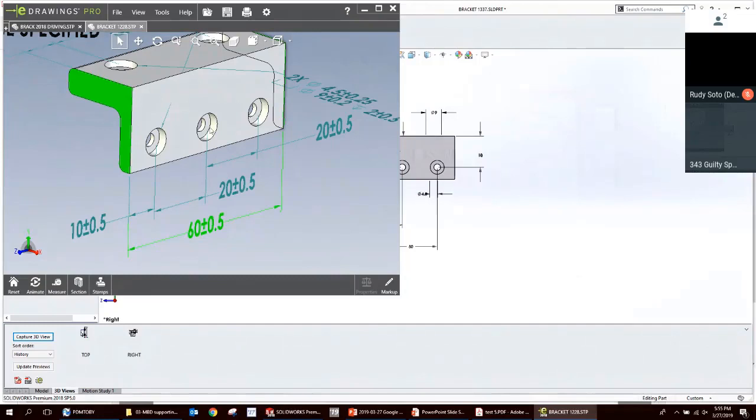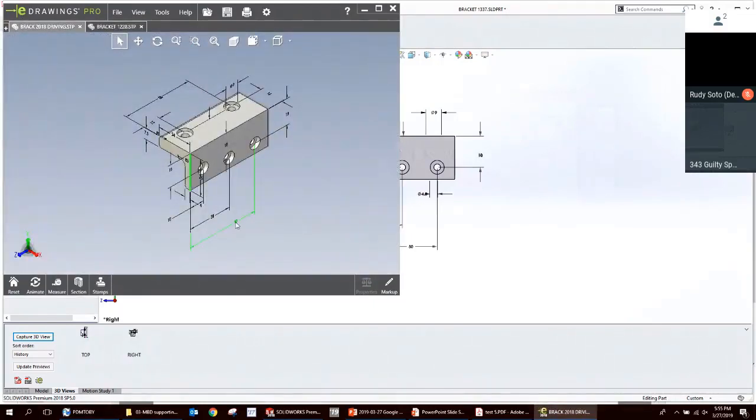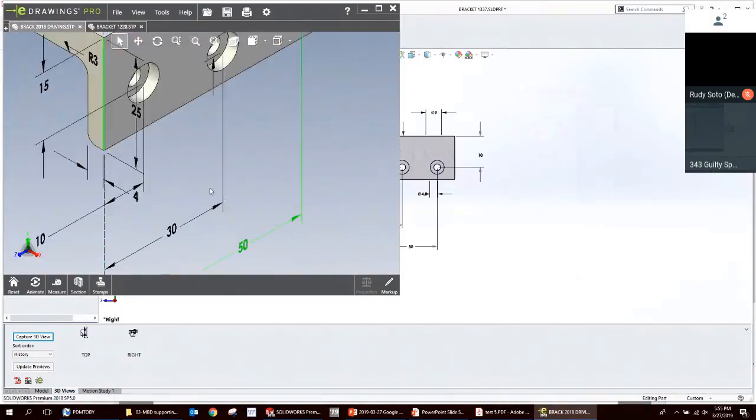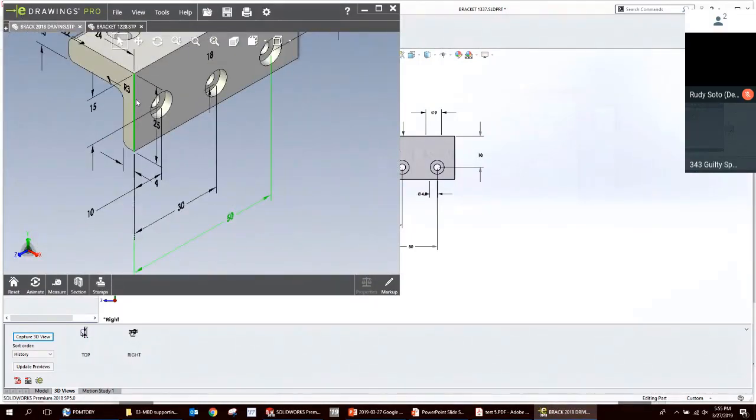This dimension is connecting those two faces. So since the driving dimensions are coming from the sketch, you're not going to get that same intelligence. It's like, this is a dimension from something theoretic, like a previously existing sketch line, to something theoretic, a previously existing sketch point. So will it still be able to be utilized by downstream machining operations if it doesn't see those faces? That's what I need to find out.